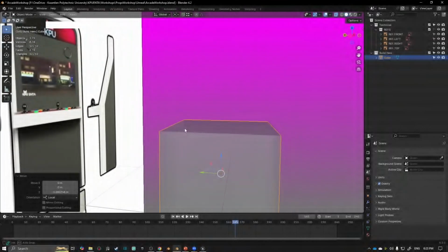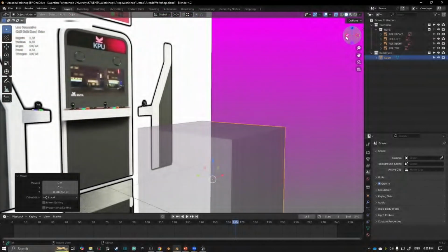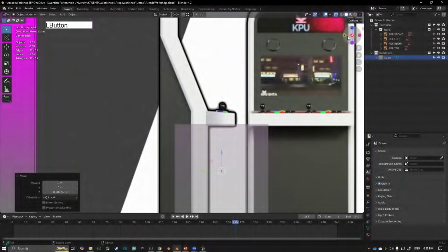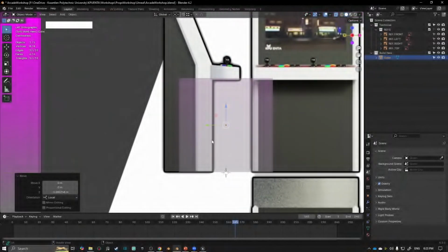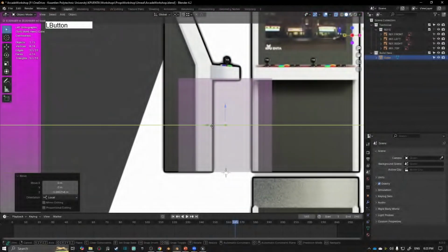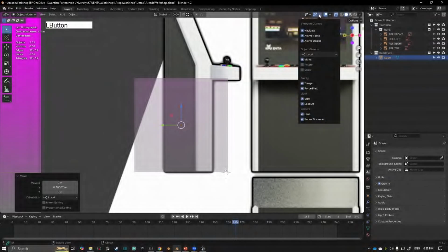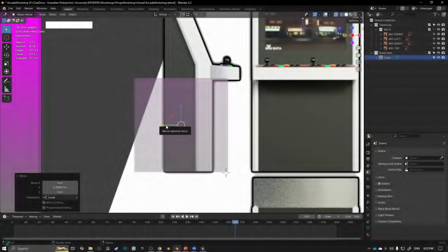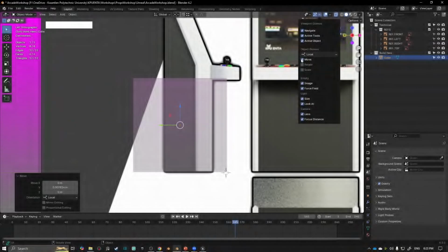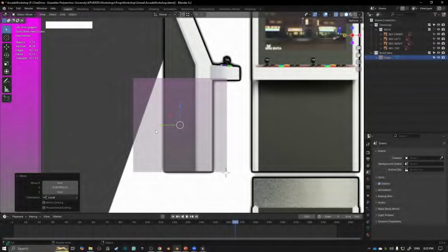So now I could try and manually manipulate this and rotate around, but I'm going to hit -X, and that's going to dump us over into our side view. I'll drag our handles. Now, in case you don't have your handles visible, go up in here to the gizmos and make sure that you turn on your move tools. It should be by default with the file that I've set up, but just in case you get lost, this is where you turn on your move.